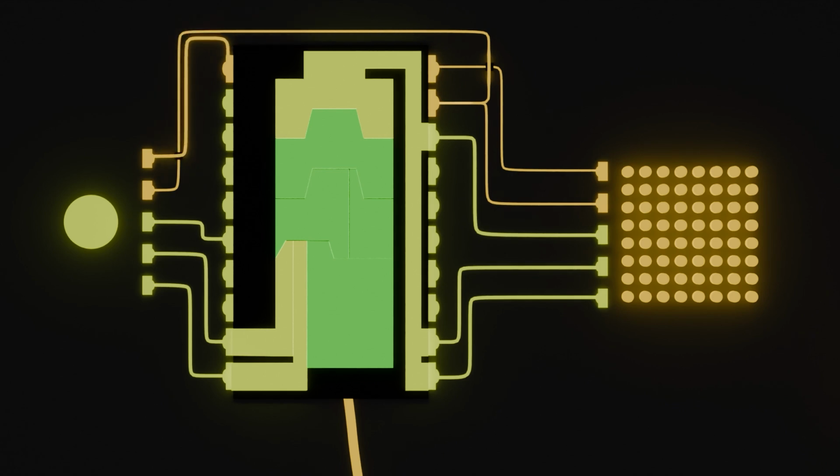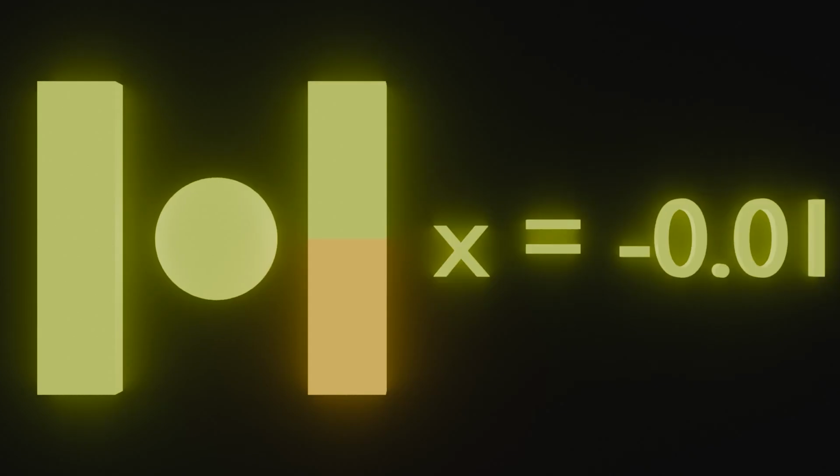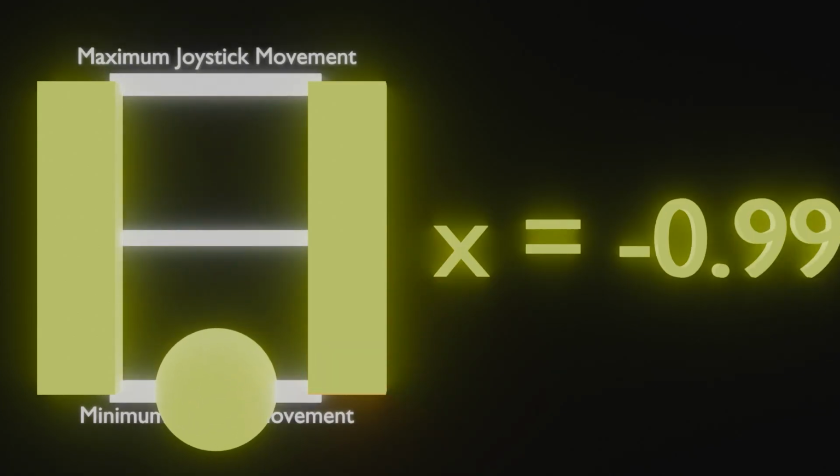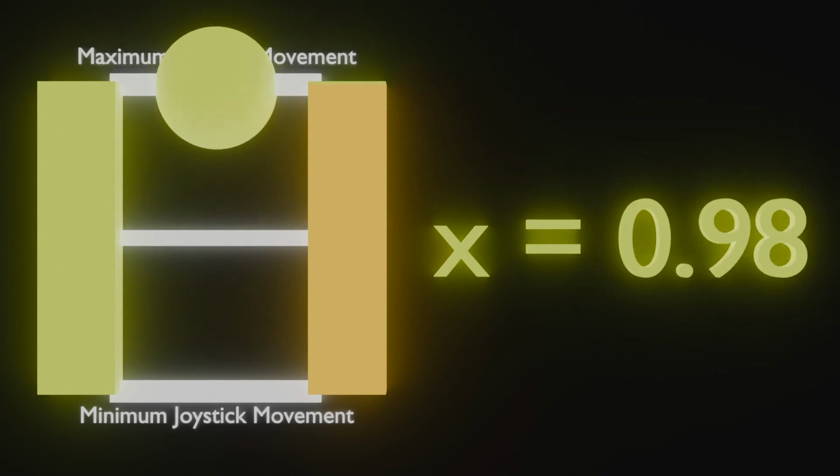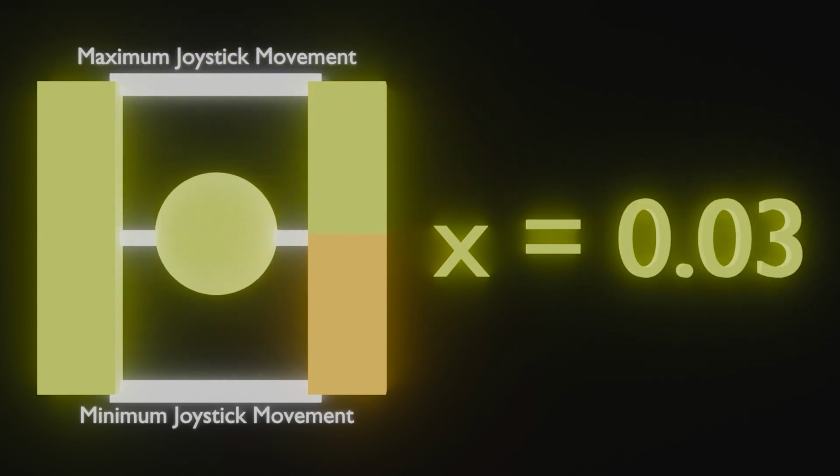That's because this joystick works by increasing and decreasing the resistance, which basically translates to changing the output voltage. And okay, think about it this way. We have our joystick into which we input the voltage. When the joystick is down, the full voltage is going through. As we move it up, less and less voltage is passing. Now we measure this and it tells us where the joystick lies.